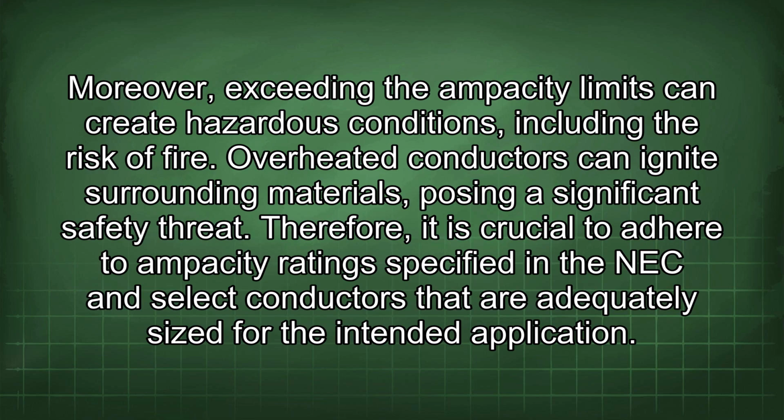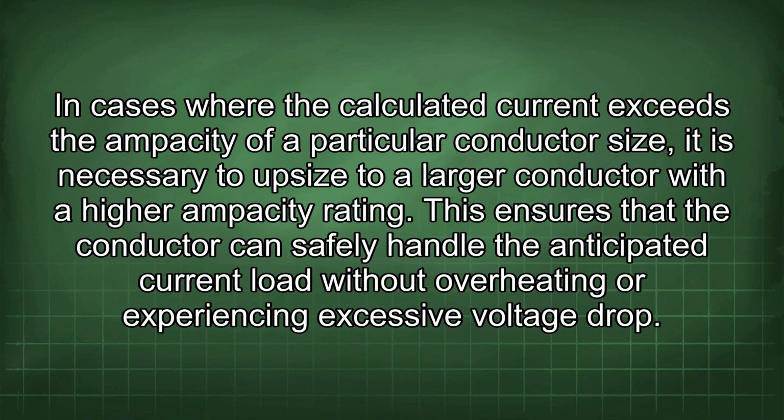Therefore, it is crucial to adhere to ampacity ratings specified in the NEC and select conductors that are adequately sized for the intended application. In cases where the calculated current exceeds the ampacity of a particular conductor size, it is necessary to upsize to a larger conductor with a higher ampacity rating. This ensures that the conductor can safely handle the anticipated current load without overheating or experiencing excessive voltage drop.